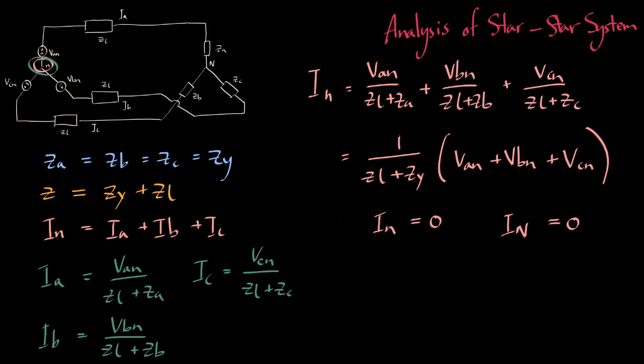Because the current at this point and at this point is identical, it's not necessary to join them. This is the reason why high voltage transmission systems use only 3 conductors. Also, take note that if these 2 neutrals were connected and there was some sort of impedance in between, the voltage drop across this impedance would be 0.